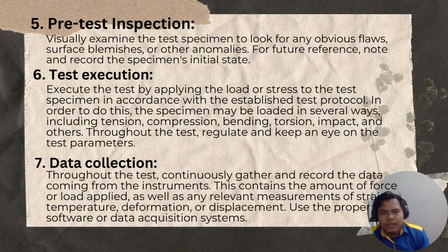Data collecting. Throughout the test, continually gather and record the data coming from the instruments. This contains the amount of force or load applied as well as any relevant measurements of strain, temperature, deformation, or displacement. Use the proper software or data system.